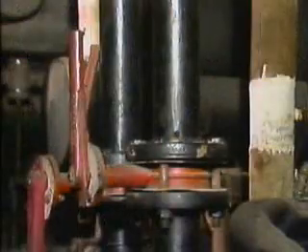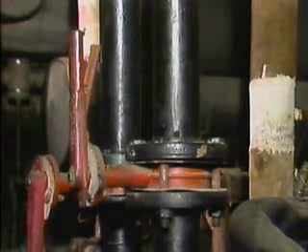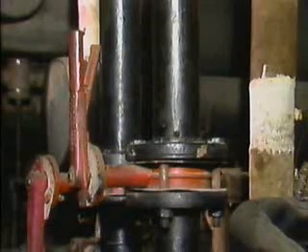A lever with a locking device is frequently used as the handle on a butterfly valve because flow through the valve can sometimes cause the disc to flutter or change positions. Locking the lever in place helps the disc resist the force of the fluid flow and stay in the proper position.